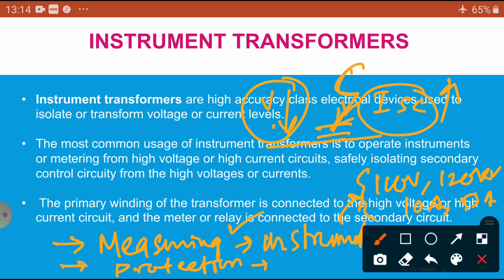So I cannot measure these currents always, continuously, 24/7, because our lines are many kilometers long. I cannot concentrate along the line. So the fault may not be avoided. Suddenly there is a heavy gale and wind comes. Some trees may fall on our lines. Our lines may break and one line falls on another line, or total lines fall on the ground.